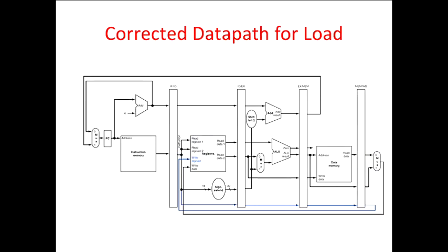So what you actually want to do is capture the register you're going to write and also register that. So take the instruction bits of the instruction you fetched and move those down the pipeline with the instructions so they stay together. So at each stage, you know the right thing to do for that instruction. Right, so you're taking a copy of the instruction bits and moving it down with the data down the pipeline. So when you get to the end of the pipeline, you know the correct register that you should write to. Okay? Is that clear to people?